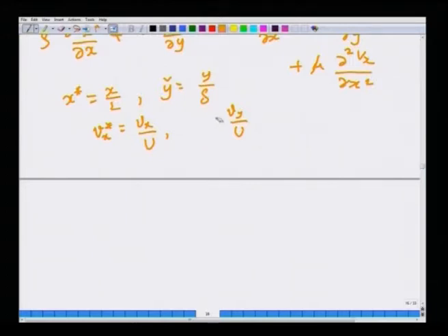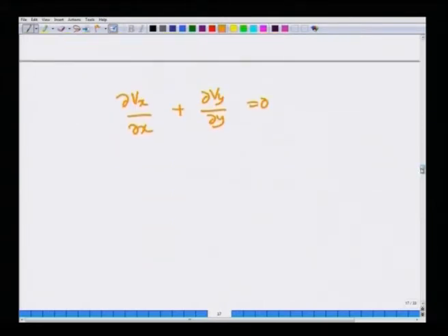If you do that, okay, so what you will get? Okay, so first we will have to worry about what is v y star, how to non-dimensionalize the normal velocity. So, let us first write down the continuity equation in Cartesian coordinates. Okay. In the x direction, we have chosen the velocity scale to be u and the length scale to be L, plus in the y direction we do not know what the velocity scale is, let us call it some v, and the length scale is delta.